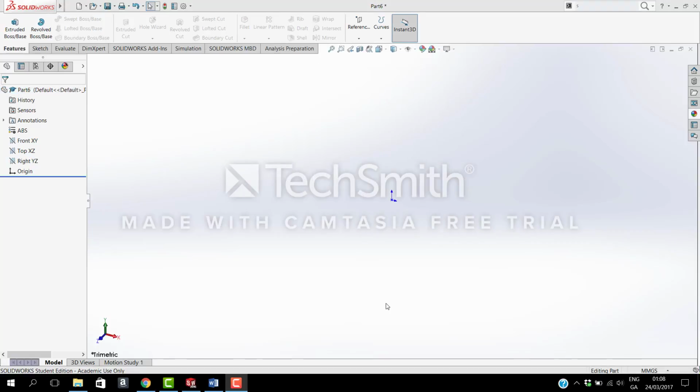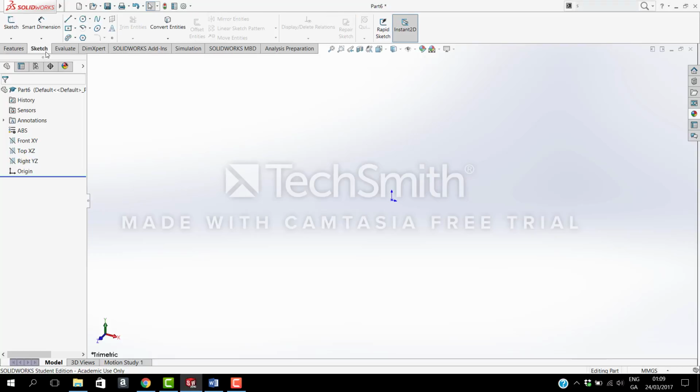For the Lego block, we will use a rectangular extrude as our base feature and the top plane as our corresponding plane. So I'll start with a sketch on the top plane. We will use a center rectangle because we want to keep the origin in the center of the model. So if we click on the Sketch tab in the Command Manager and click the drop-down arrow beside the rectangular sketch command, we can choose the center rectangle.